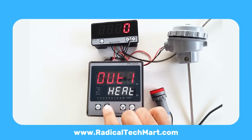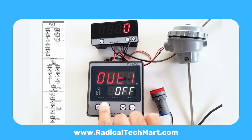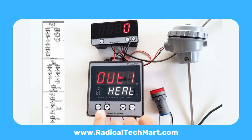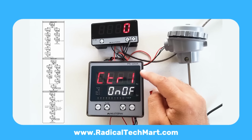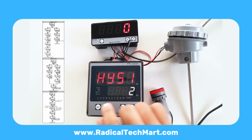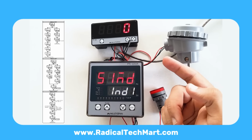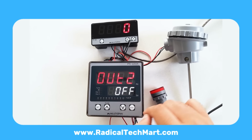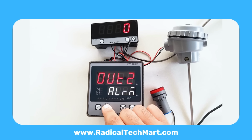R1 menu: choose how relay 1 behaves. Heat, forward action. Cool, reverse action. Alarm, off, disabled. Then set control 1 to on-off, since analog output is handling PID. Set hysteresis and choose individual or relative to analog SP, as needed. R2 menu: if unwired, keep off, otherwise, set heat, cool, alarm per your application.